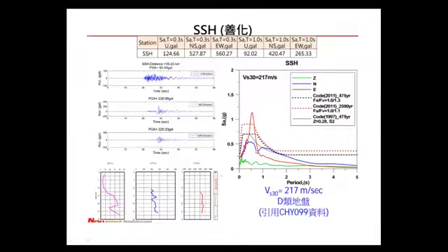As we move toward the west, we'll be going to a site in the foothills. The VS30 will be 200 meters per second, about say 600 to 650 feet per second. One thing observed in the time history is that instead of 8 seconds, look how long it is extended, probably to 15 seconds. And you also have the strong velocity pulse at about 0.5 to 0.6 seconds. And also the east-west, the red, is much higher than the blue line.